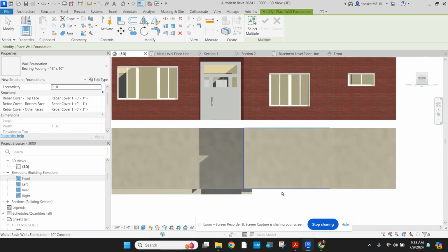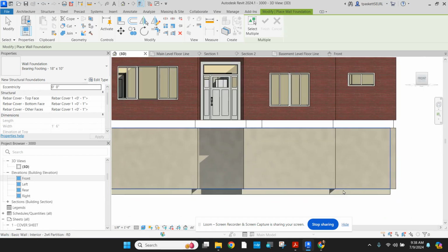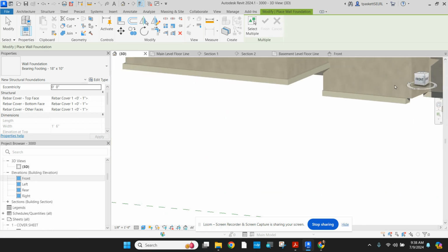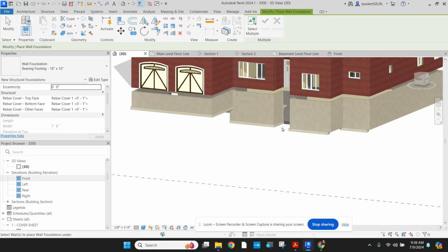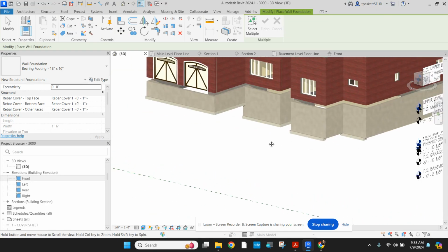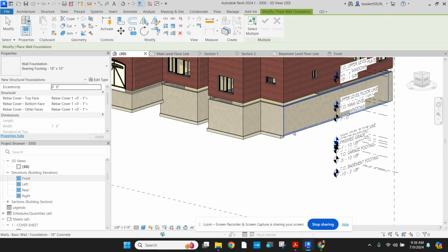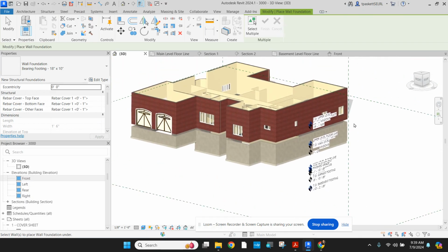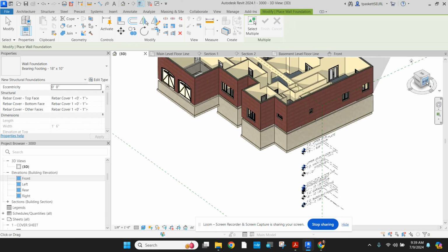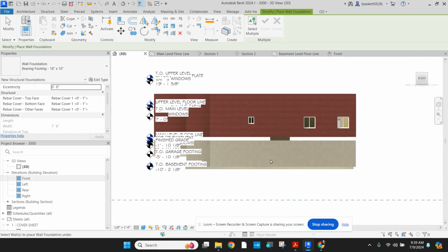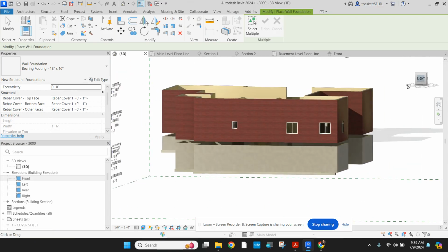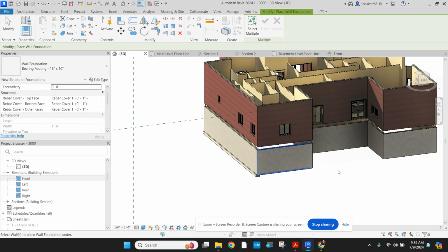so that you can see them all. And it just takes a little bit of patience. Actually takes a lot of patience. So we put all these walls back in with their footings. Yay. And we'll swing it around to the back. And swing this one. We just want to go ahead and click every wall. Make sure there's a footing on the bottom of it. That's our goal.